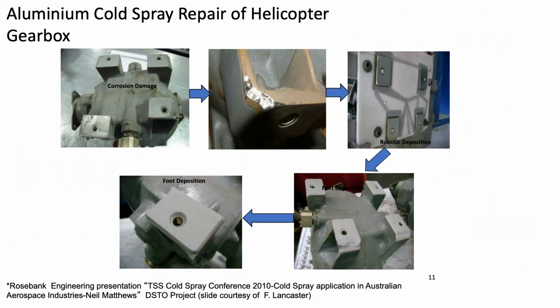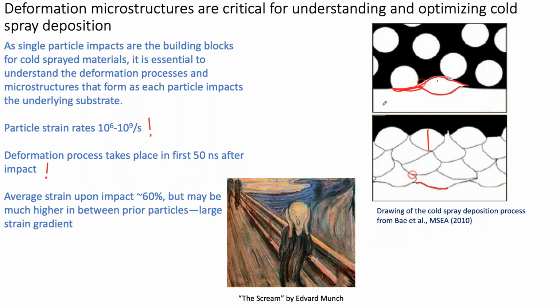sorry, trying to go back to where I was talking about that. By the way, this is a crude estimate, although I keep seeing these numbers pop up throughout the cold spray literature, so I don't think I'm that far away. There are people that do detailed mechanics simulations of this process, and they arrive at this range of numbers as well. There are those that predict, and maybe even some limited observations of evidence showing, potential localized melting, particularly those that ascribe to an adiabatic shear instability model, where you get very localized heating.